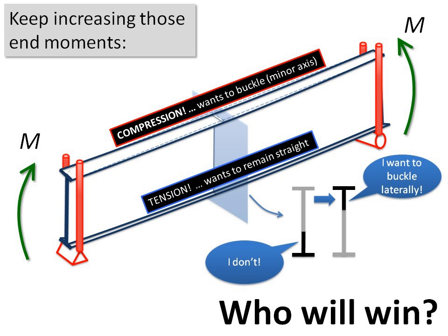And like I said, that top flange, all the way across, is all in compression, and as we know from lecture 1 and 2, when something's in compression, it wants to buckle. In this case, it has one of two possibilities. It could either buckle up and down, which would require us to bend the section about its major axis, or it could buckle about its minor axis, and that's certainly the smaller path.